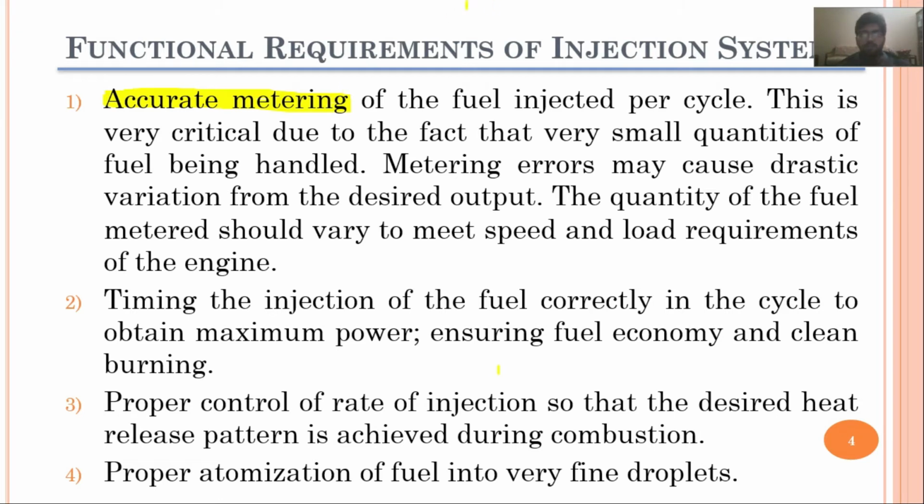So moving towards the next function, the timely injection of the fuel. Now this function is also very important. It means that when the piston is reaching the top dead center, usually what happens is, before reaching the top dead center, the fuel injection starts, and this timing of the fuel injection is very important.